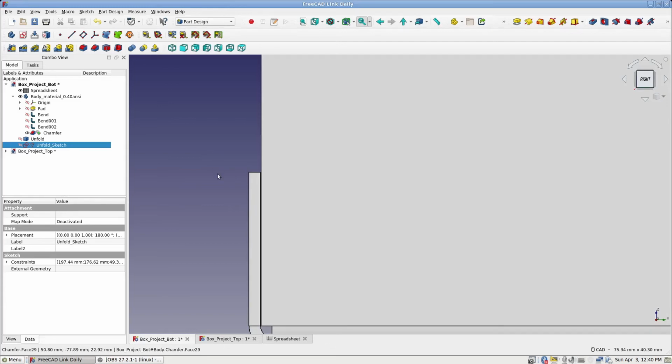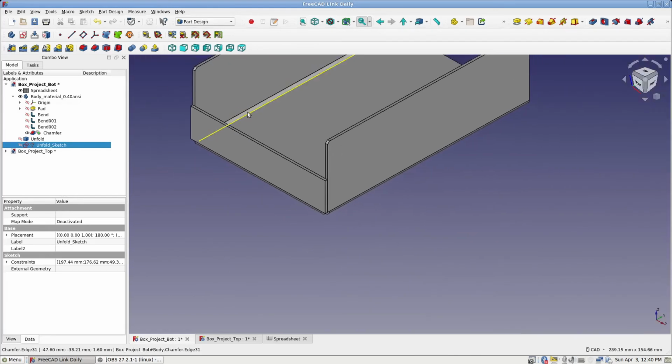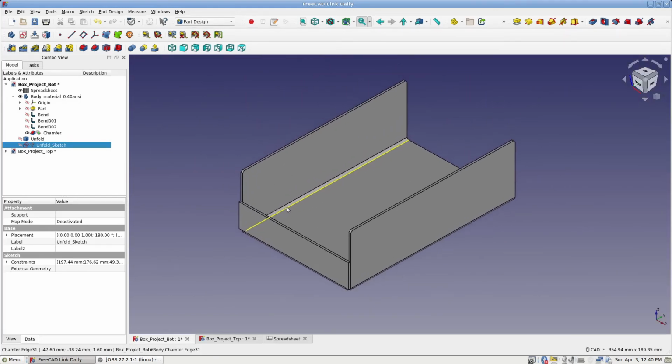So when you specify the space of this tab and you do it just on the setback on the bend, and this lays right up against here and there's no gap in there, the unfold tool is going to complain. It's not going to work properly. So that changes the flat layout very, very slightly, but it's such a tiny amount that it doesn't really much matter. So I just wanted to make sure that you understand that.